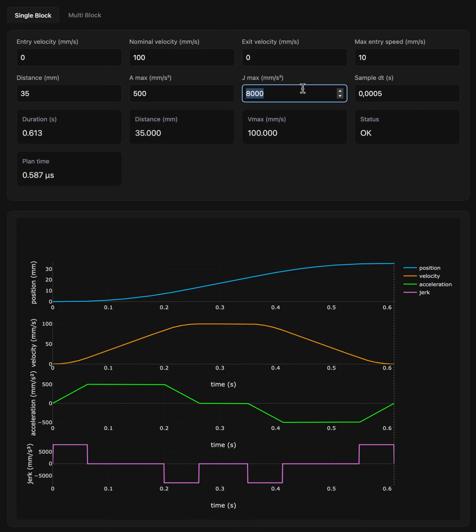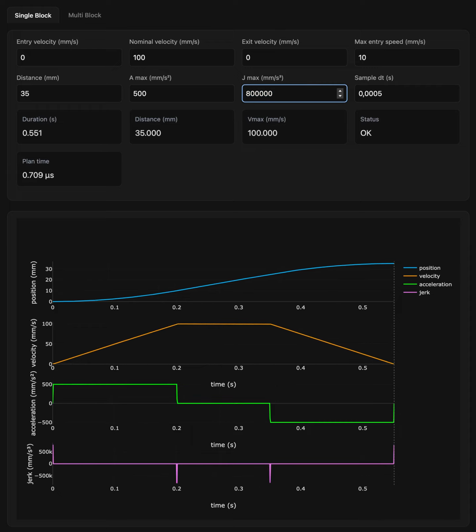The way S-curves work, like Poly 5 and Poly 6, is they start with the trapezoidal profile, and then they just fit a polynomial to the acceleration and to the deceleration phase. This polynomial has the same initial and final speed and the same average acceleration, and it travels the same distance as the linear ramp does, but has a smooth acceleration.